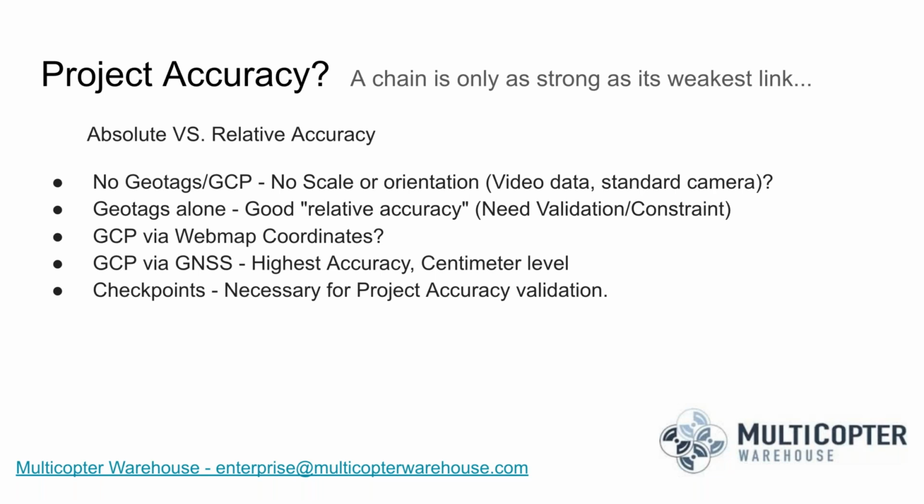And a thing you'll hear a lot with Pix4D, or maybe if you're also using RTK, or real-time kinematic drones, is the term checkpoints. A checkpoint is essentially exactly like a ground control point, except the value or the location of that isn't fully exposed to the software until after the processing is complete. Then the software looks to see how accurate the checkpoint value is to the calculated value at that location, and that'll give you ultimately the accuracy of your project.